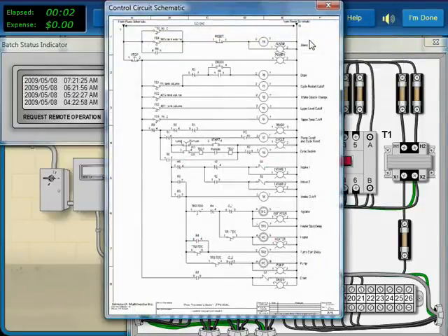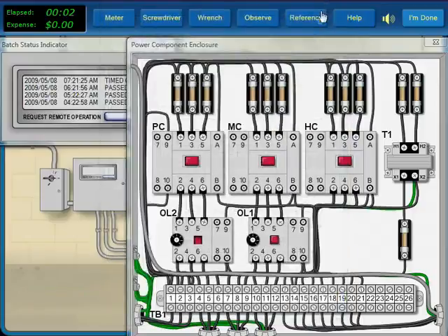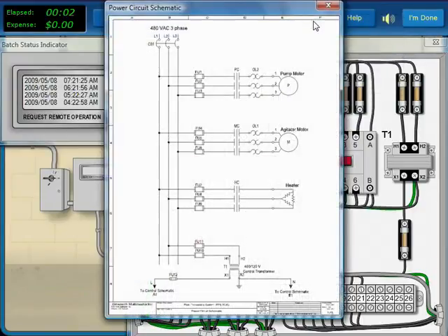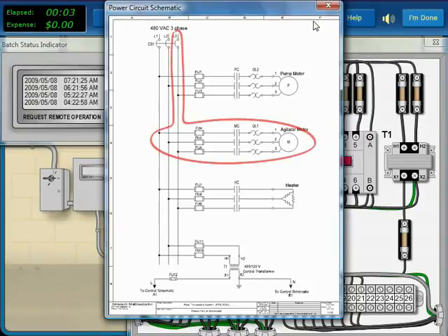The control portion of the circuit can be excluded because it works as expected. In the power circuit, we can exclude the 2 phases which supply the control circuit. Also, since the overload trips, we know that there is current in at least 1 phase of the agitator circuit. Therefore, the problem area is confined to the agitator power circuit and the 3rd supply phase.